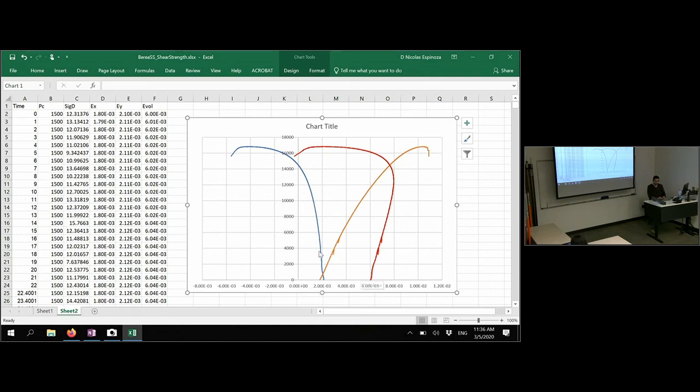And here, we see the loading, then you have to compute the Young modulus for that. We see 2 unloaded cycles, you have to compute that Young modulus as well. And the new thing from here is that you're going to have to also compute this volumetric strain curve. And this volumetric strain curve tells you when the rock starts to fail.